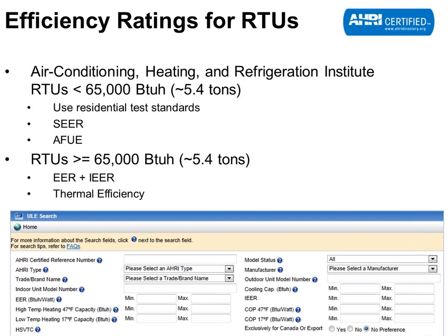Basically what that does is we test it at 4 different points: 100% capacity, 75, 50, and 25%. So we tested these 4 different points. We got these 4 buckets of tests that we do. And the 2 middle ones, the 50 and 75, are heavily weighted. And the 25 and 100% operating points are very lowly weighted. Only a few percent of the hours of the test go into that bucket. So basically saying how efficient are you at these mid-tier ranges, because that's where you're going to spend most of your operating life.